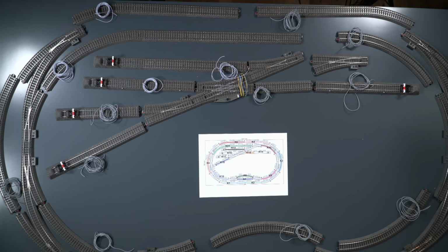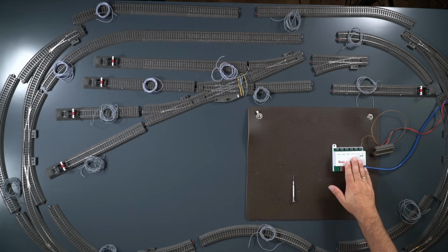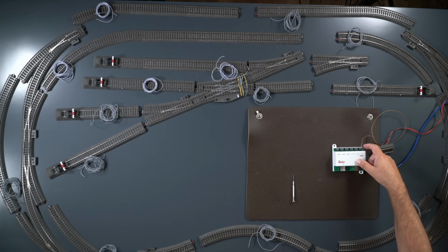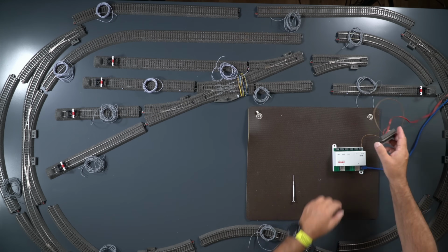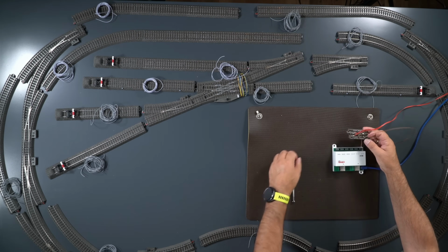And now I'll show you a trick, because I absolutely want to make sure before I screw the setup together that the contacts really work. Before we permanently install the contact rails on the setup, it's always helpful to test all the contact rails for functionality first. This is relatively easy to do by setting up a small test environment like this. Of course, don't forget my S feedback module, very important. Connect the ground coming from the central unit, and then also a track that is supplied directly from the central unit as a supply track.